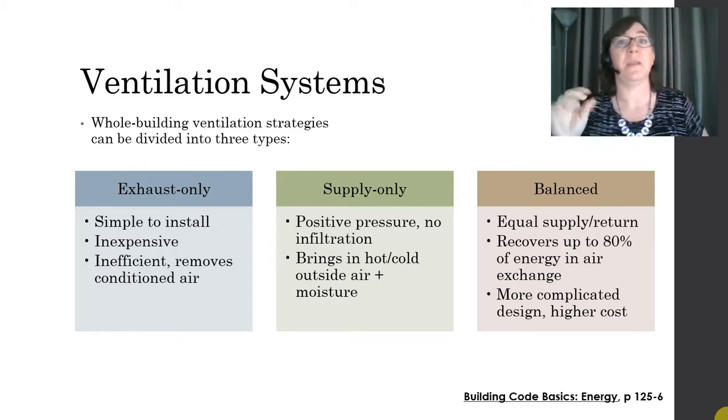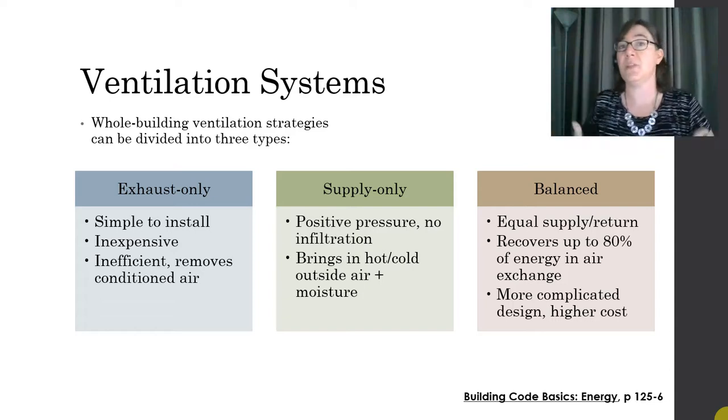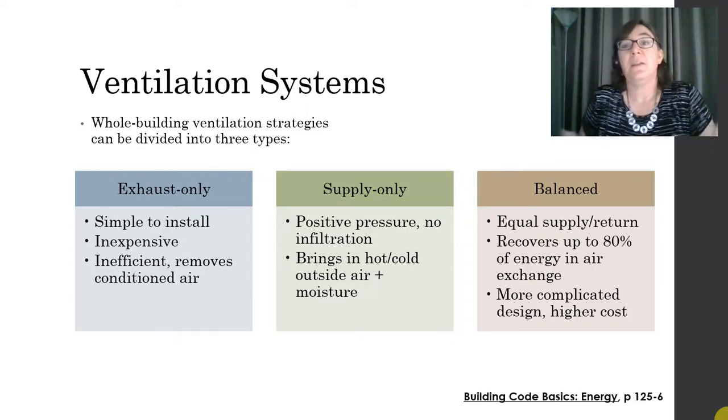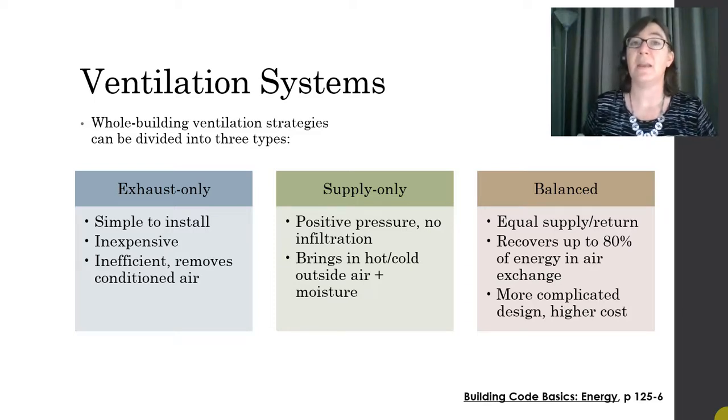The advantage of this system is that you can use an HRV or an ERV equipment to recover up to 80% of the energy in your air exchange. So it's got a high efficiency. The downside is that it's a more complicated design and therefore has a higher initial cost.